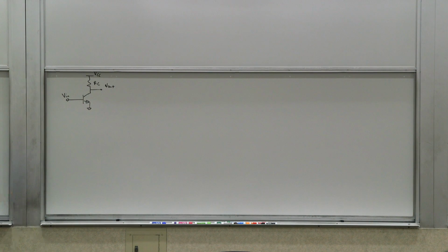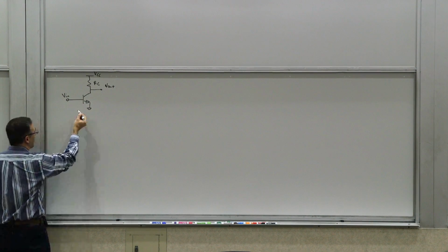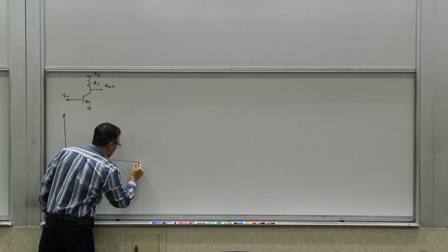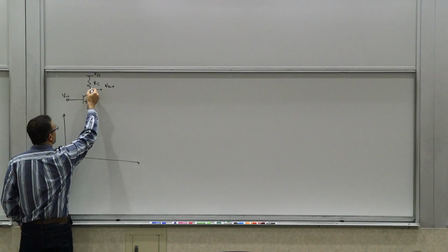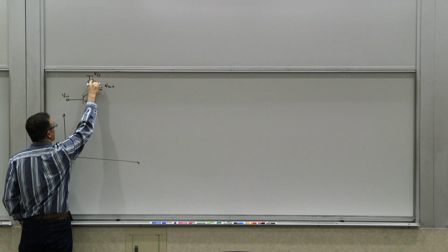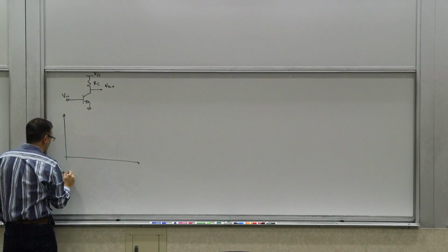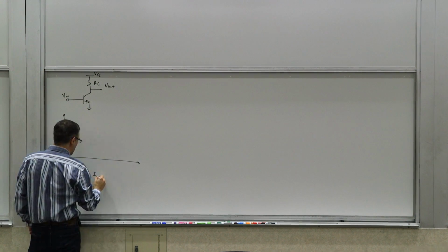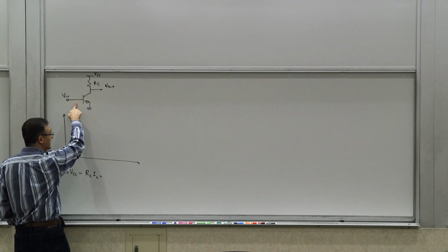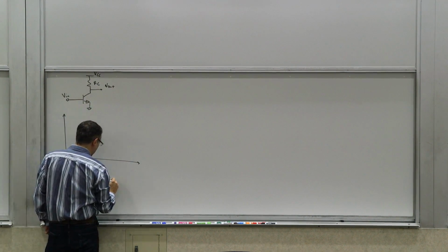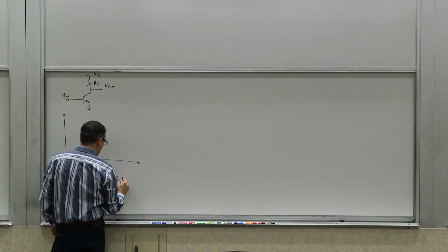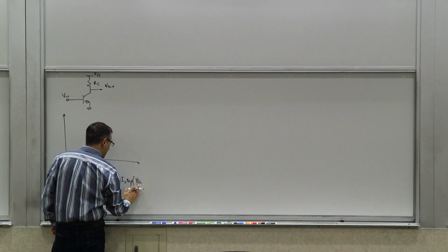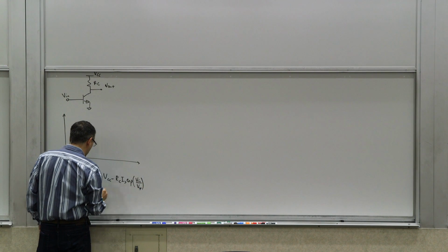Now, of course, one of the things we saw when we looked at that was that even from a large signal perspective, if you just think about this as a Vin, Vout characteristic, you can draw the Vin, Vout characteristic, and we did derive it. Basically, you can write the output voltage as VCC minus the voltage drop across here. So Vout was VCC minus RC times the collector current, which is related to the base emitter voltage, which is now Vin. And we know how that dependence works. We know that it's primarily exponential. So it's IS e to Vin over Vt, the thermal voltage, kT over q.